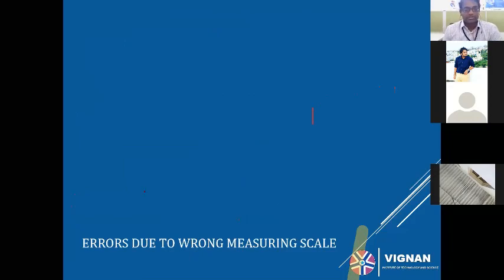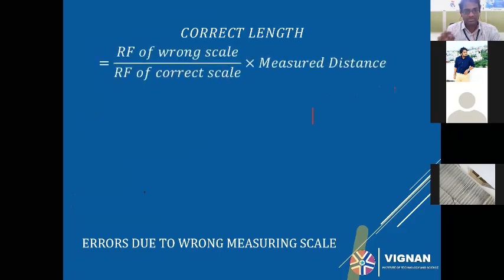So we have two equations, right? One is if the map has shrunk and if you want to calculate the correct line, what is the equation you will use is, please write it down, right? I can repeat, you have a map, right? You know the wrong scale, you know the correct scale. In the previous case, the scale is same. Now the scale is also different. You have a wrong scale, you have a correct scale, and you have a measured distance, and you wanted to calculate the correct length. Measured distance to ground length, right?